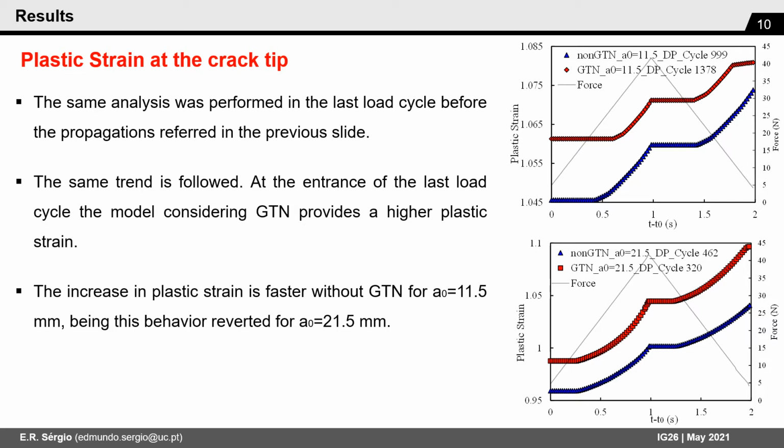Moreover, on the unloading phase of the cycle, the trend is repeated and the difference in plastic strain keeps decreasing. At the end of the cycle, the curve of the model with GTN suffers a kind of planing, this behavior being associated with the occurrence of crack closure.